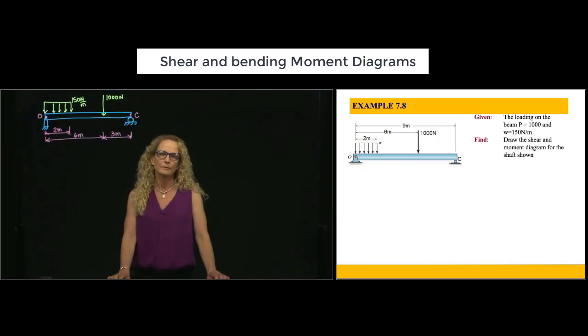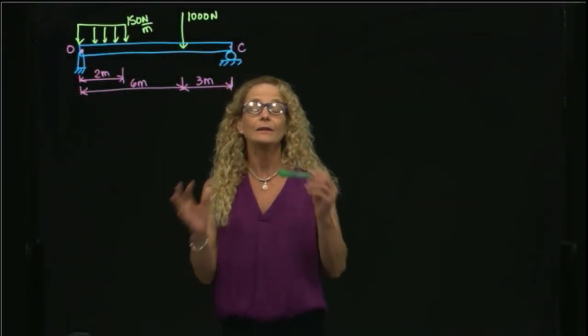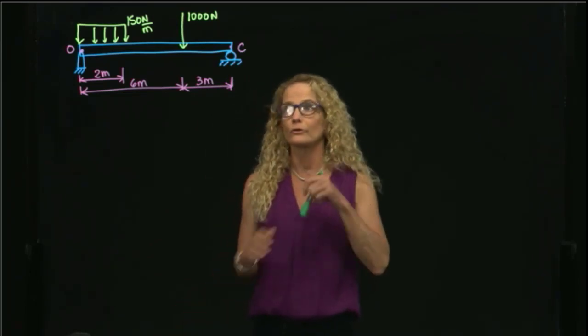This is problem 7.8, and we are calculating the internal forces in this beam. The internal forces will be the axial force, the shear force, and the moment. The first step in calculating the internal forces is to calculate the external forces.